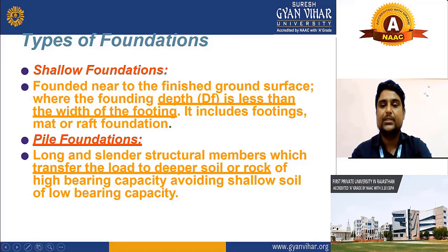Shallow foundation means where we don't require too much bearing capacity. If you are building a very high rise building, there you need to build a deep foundation, because the load of the structure will be more. In such a case, you cannot make a shallow foundation.